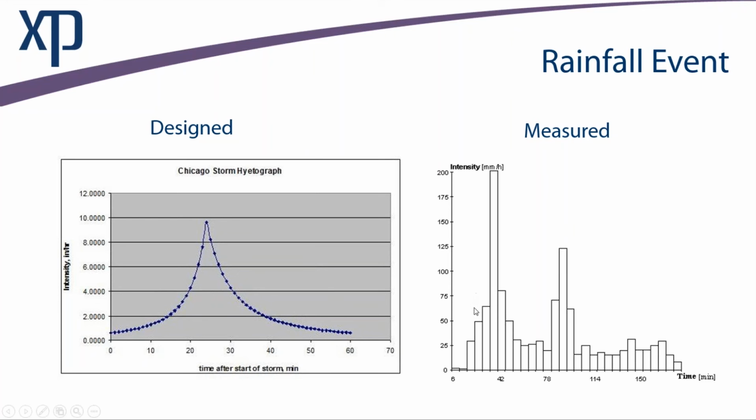And why is it important? Well, it's important because of some of the things we've talked about already. I might have a pretty high peak, a pretty high onset of a fair amount of flow that tapers off, and my network may be able to handle it. Maybe I've got enough storage in my stormwater network that it doesn't overflow or doesn't overflow much, and my creek is able to accept some of the flow, and things start to taper down, and then my second event hits. Well, the ground has already reached saturation point, and the channel is almost full, and the stormwater network's almost full, and even though this is a lesser peak, the second time around it can cause a tremendous amount of flooding.